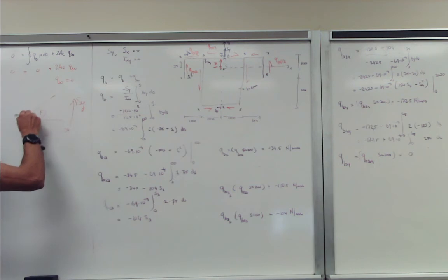So what is it? Recall the definition of shear center. What is the shear center? Definition of it. I would say it lies in that corner in between the two. Correct. Why? The moments are acting on the other ends, and because of that, you're going to get shear flow.